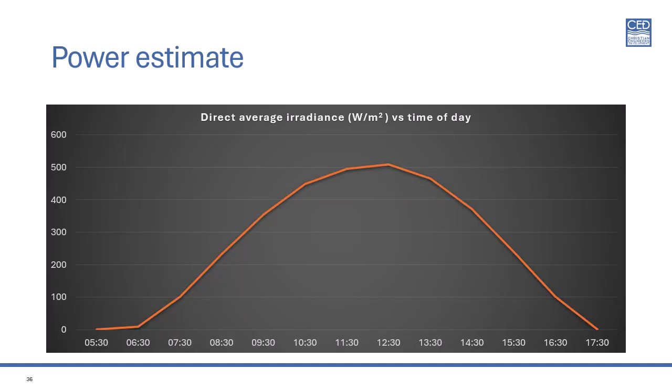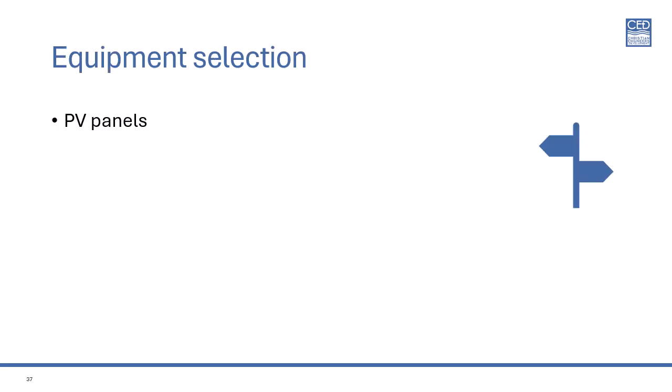We're using the minimum values rather than the annual values because the site is off-grid and so must operate every month of the year. Obviously, the available solar power varies across the day, rising from dawn to a peak midday and then diminishing back down towards dusk again. So we're going to take a look at the solar panels, the inverters and the batteries that might be required to achieve the energy requirements at that site.